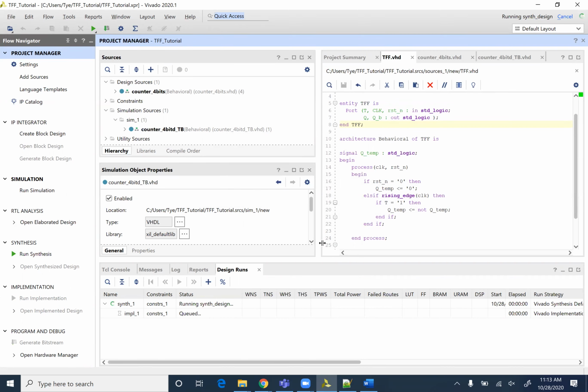It is possible to accidentally click generate bitstream, and if you click the wrong buttons, because synthesis isn't ready, it will pull the old synthesis. So you may have thought you updated it, but you didn't allow synthesis to rerun, and then you can cause it to have problems. So that is something to be aware of when you generate bitstream.